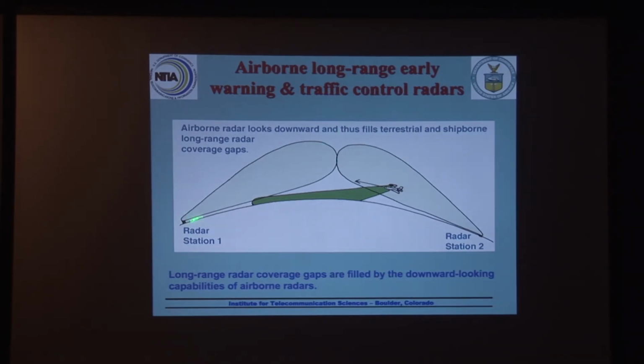So here we see the classical coverage from the ground stations drawn, as I said, very, very schematically. Now we see the radar antenna mounted on an AWACS aircraft, and I've exaggerated to some extent the downward-looking angle, but my point in this diagram is to show that this aircraft, which is flying through like this, and which has this thing rotating around, being a long-range radar about every 10 seconds, it's sweeping this beam across the Earth's surface like this every 10 seconds while it's flying.